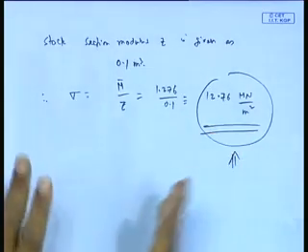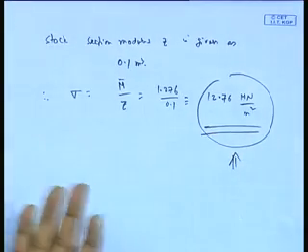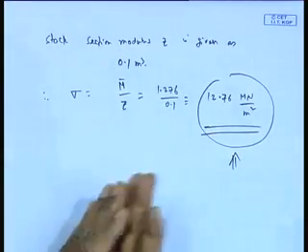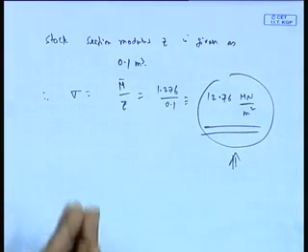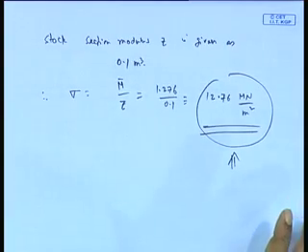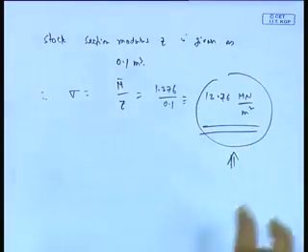See, this problem is very simple. What I tried to do quickly is essentially give an idea regarding the kind of stresses that will come on your stock. You can be off by say 10%, 20% depending on what formula you use, but for design purposes it is good enough initially. And these kinds of numbers should give you a feel of the kind of stresses that we deal with even in rudder stock and rudder force. So this is just a simple example.